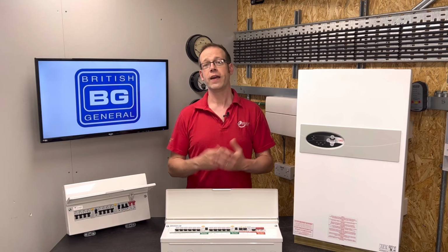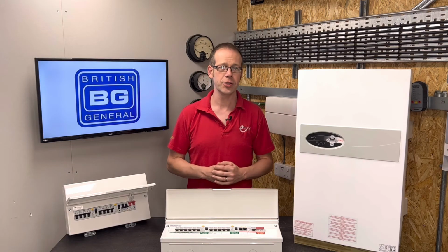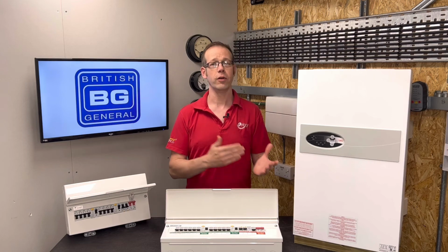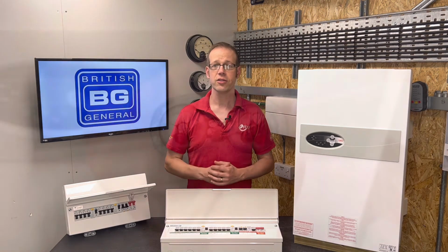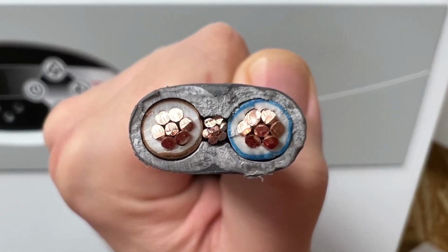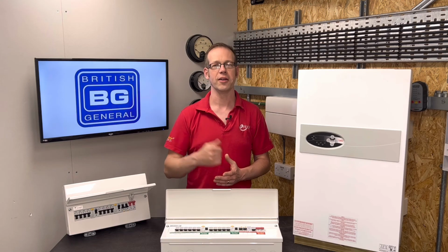Okay, so we've found the size of cable that we need to install to supply our boiler. However, there are other things that we need to check before we can install that cable. These include the volt drop, the earth fault loop impedance of the circuit, and in some circumstances, if the size of the CPC is acceptable. But we're going to cover that in the next part of this training package, so please do make sure that you check that out when it gets released.